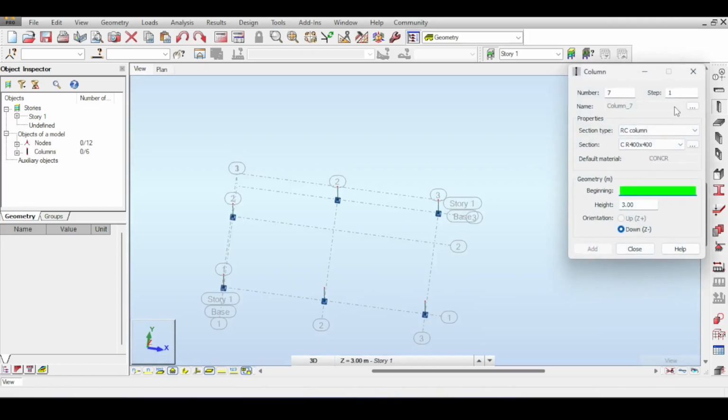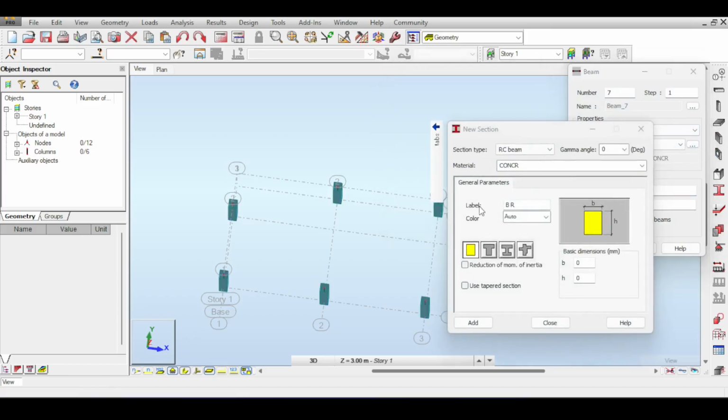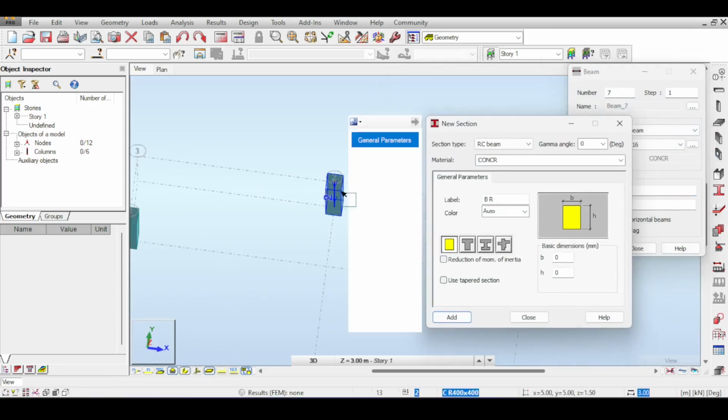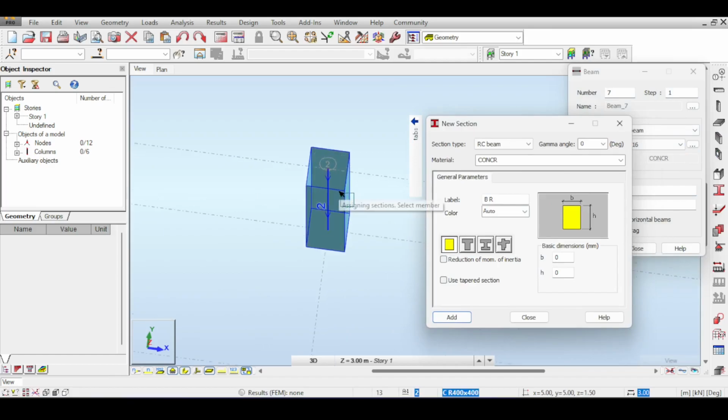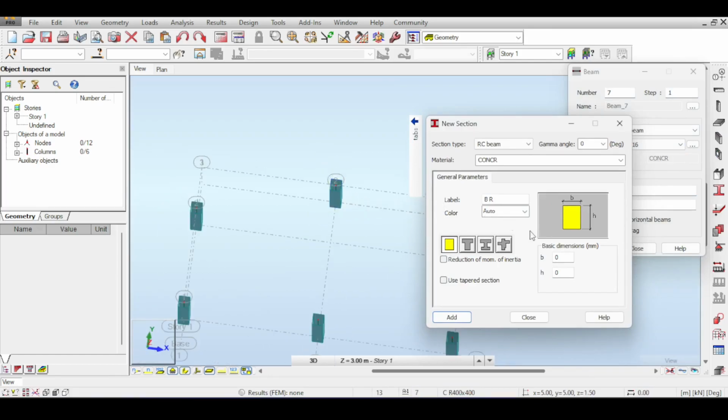Now let's put some beams. Well, I'm going to put a reinforced concrete beam here. And let's go to a beam here. Let's select reinforced concrete beam. I'm going to assume a beam of, I don't know, like, now wait, I made a concrete column like this. So my beam should be less than 400 millimeter in width to be able to connect with the column. I'll choose a beam width of 250 with a height of 400 millimeters. This is a drop beam.